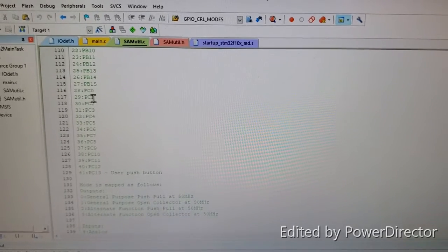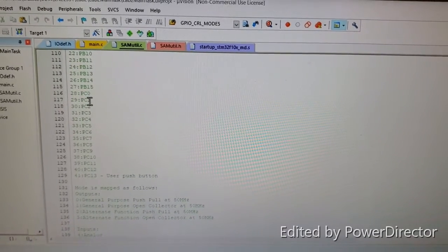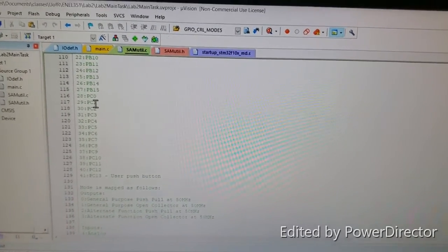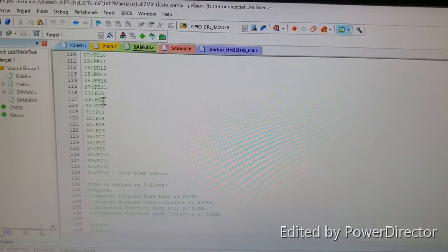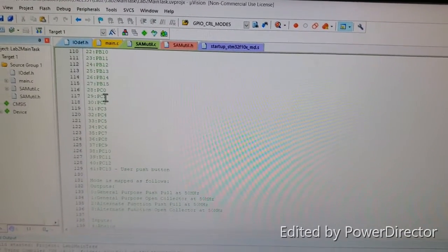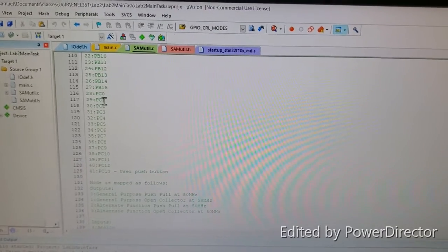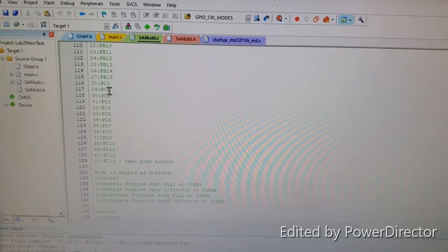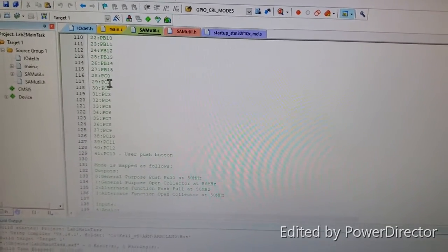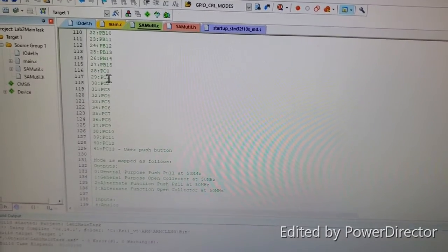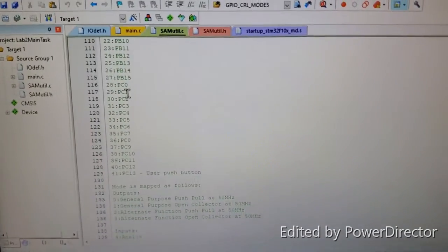And this, of course, takes into account any hardware conflicts that are potentially on the board we're using, such as PA2 and 3. By default, their solder bridges are left open because they're really only meant to be used as a UART connection and not as general I/O. PA, where is it?